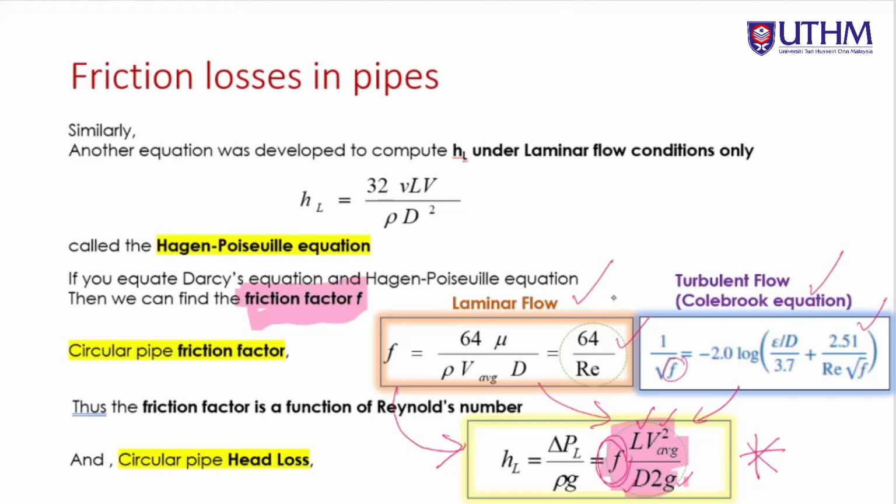Okay, this is important, right? The friction factor for laminar, the friction factor for turbulent, and also the equation to calculate the head loss. Actually, to find the friction factor, there are two methods. Either we use these equations in order to find the friction factor, or the other method is by using a diagram.